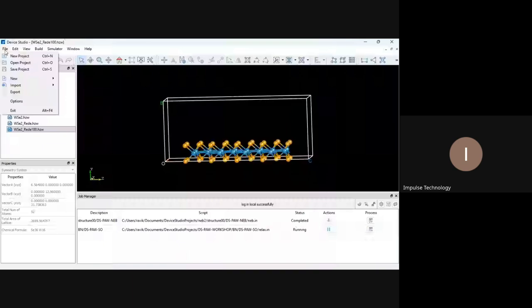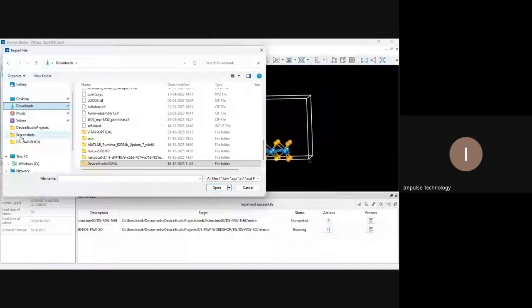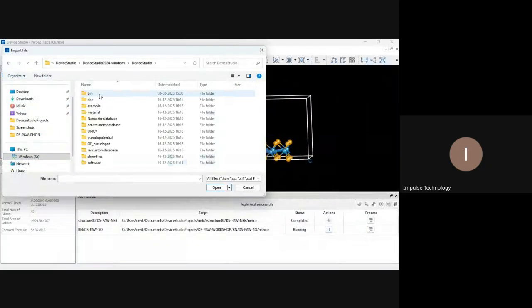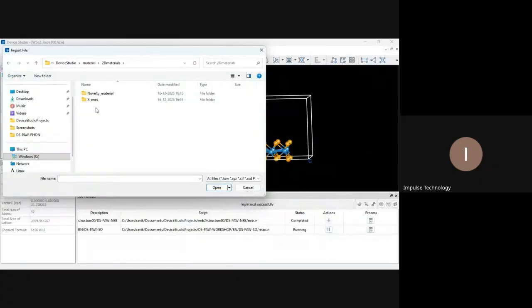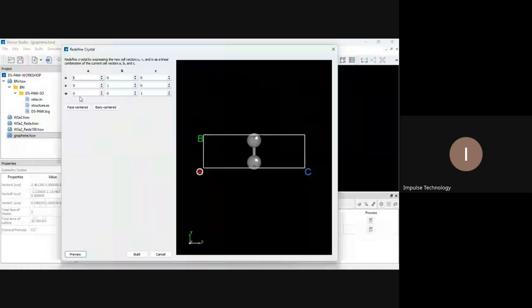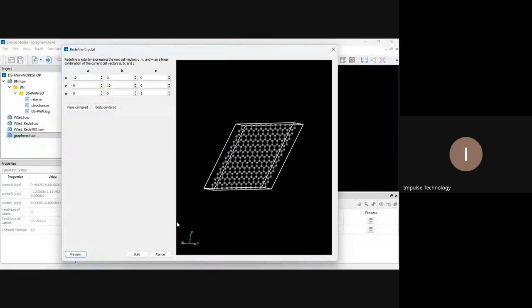Like to create 4-probe devices. In the earlier session, we went through the Nanodcal software where we only created 2-terminal devices. Let's here create the four terminal device. And graphene, redefine, and go for 12 cross 12 and create a graphene nanosheet.